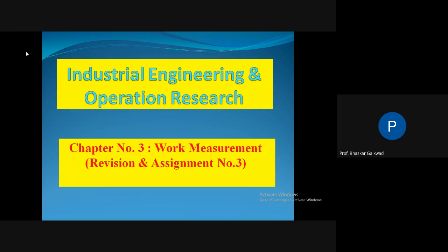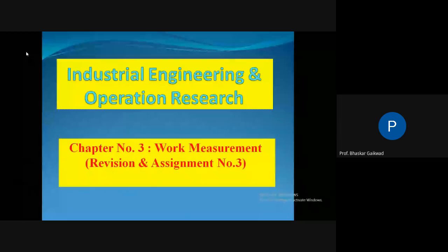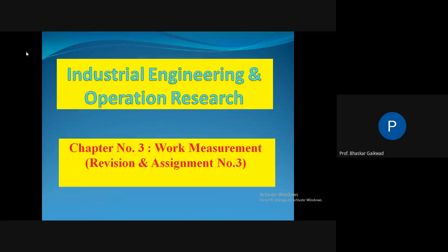What are the steps of this time study? We need to record, then examine and decide the times, and after this we go for calculation of the normal time. You can use the standard formula: normal time plus allowance is your standard time. Okay.